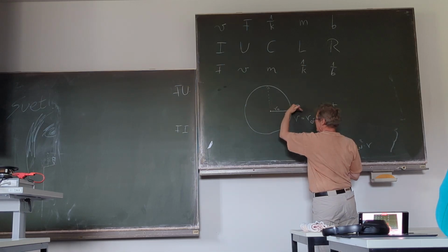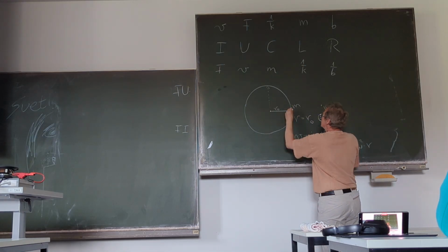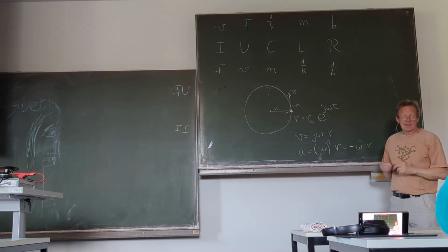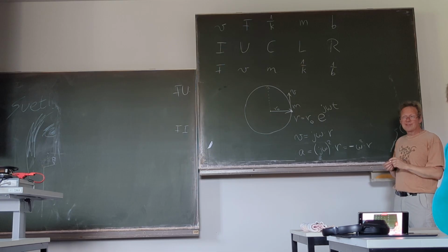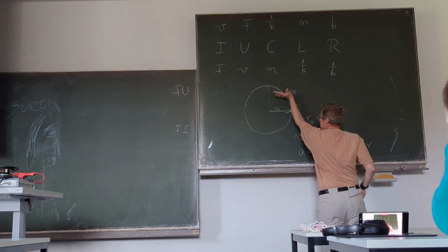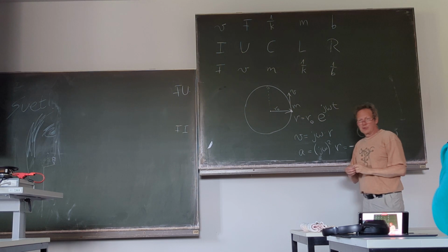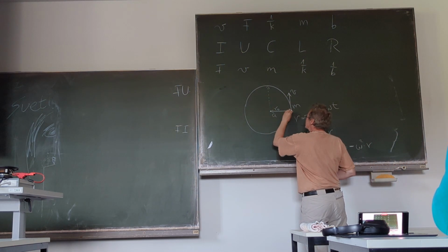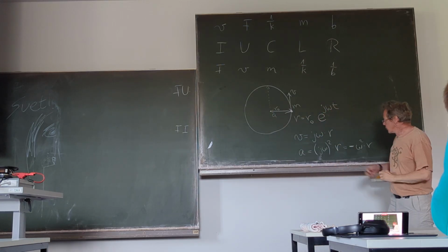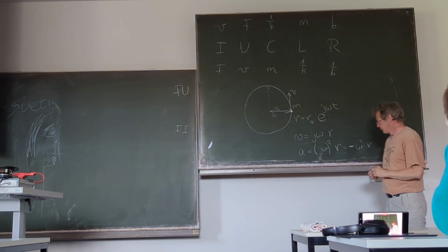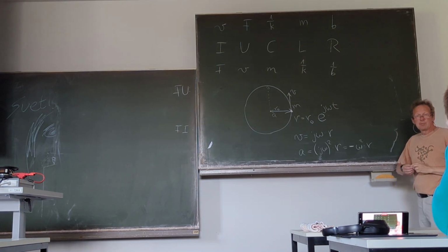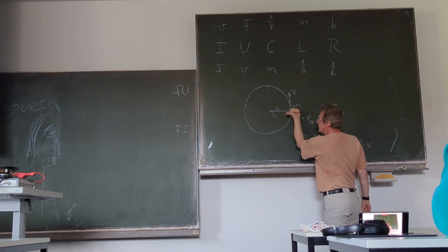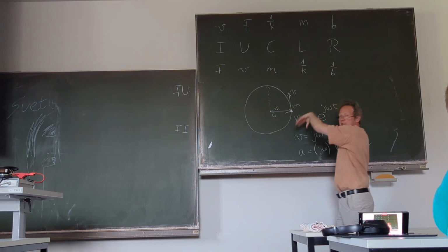So this was the original direction, a 90 degree shift gives a velocity in this direction, and the second derivative means another shift of 90 degrees counterclockwise, and that points inside. So acceleration goes in parallel to your vector, but inside. That makes sense because for the centrifugal force we have to push this mass inside, otherwise it would just vanish somewhere else.